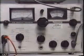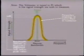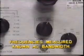When the signal frequencies are known, then a selective voltmeter can be used to check the signal strength at any selected frequency. In practice, the instrument is set up to respond to a band of frequencies either side of the selected frequency. The selective voltmeter actually filters out all other frequencies. The range of frequencies measured is known as the bandwidth.